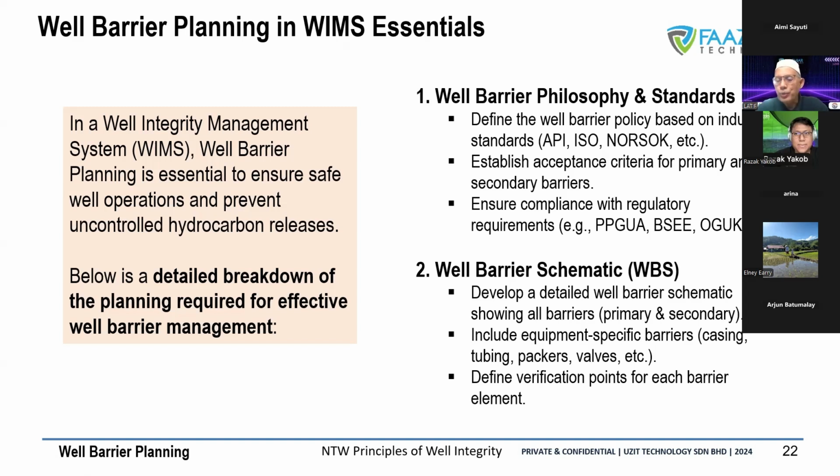This is always an issue for us in the early stage. We don't have the system to record those barriers in time. So whenever somebody does a repair, for example, we have well A, we have completed well A, and then maybe after 1 year, there is some requirement to isolate a certain zone, because they want to produce from one particular zone, so they want to stop one of the flowing barriers between the strings. So they close what they call the side sliding door, so that they produce only from the bottom part.